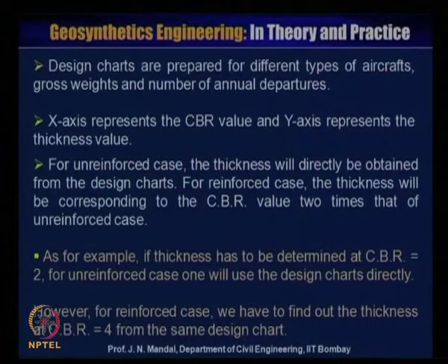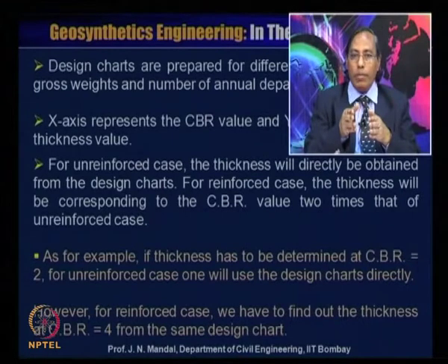So design charts are prepared for different types of aircraft, gross weight, and number of annual departures. The x-axis represents the CBR value and the y-axis represents the thickness of the pavement. For the unreinforced case, the thickness will be obtained directly from the design chart. For the reinforced case, the thickness will correspond to a CBR value 2 times that of the unreinforced case.